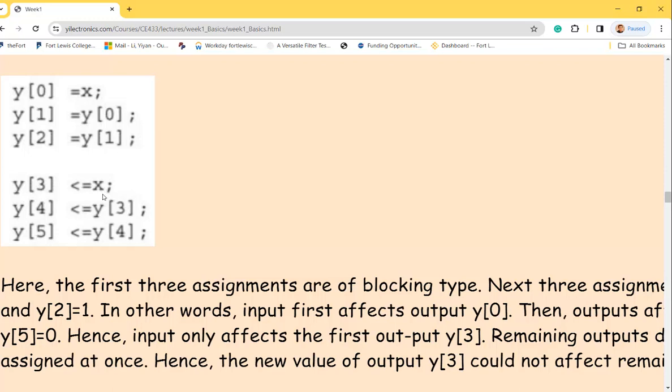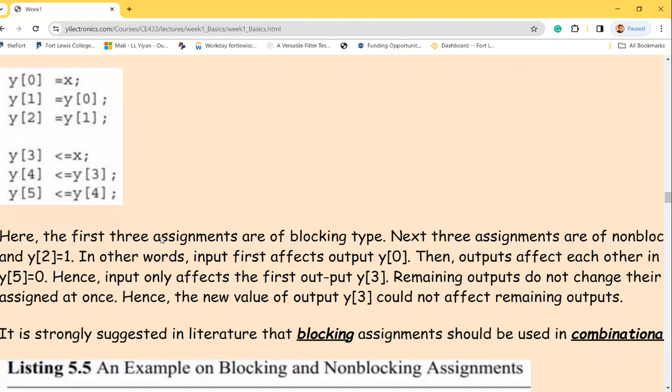It's going to be a digital circuit instead of an instruction memory, like you're taking out every single instruction line by line. Make sure that you understand the difference over here. So for example, they can still be executed sequentially by a clock. That's why you need a sequential circuit. You have a clock that controls all the D flip-flops; you turn it on, you do that once, and if you don't turn on the second stage, if no clock arrives, it won't be executed. It's okay if you don't know what's going on now, but later you will.